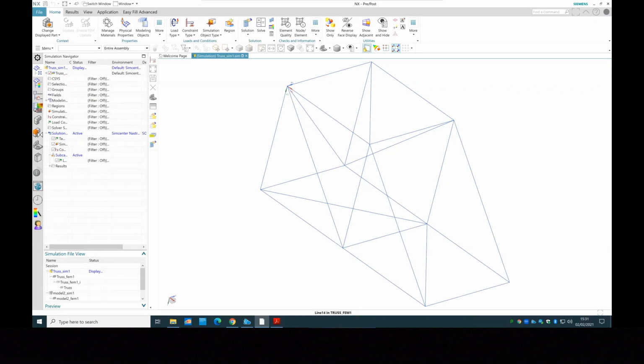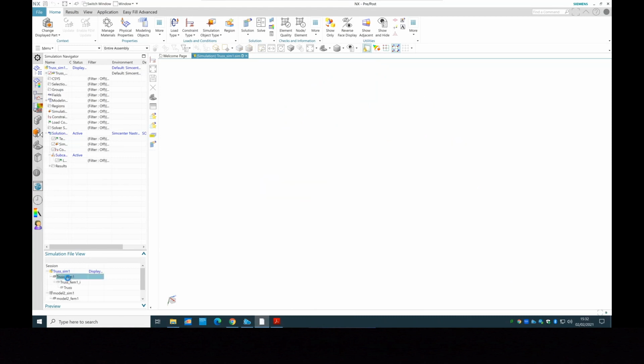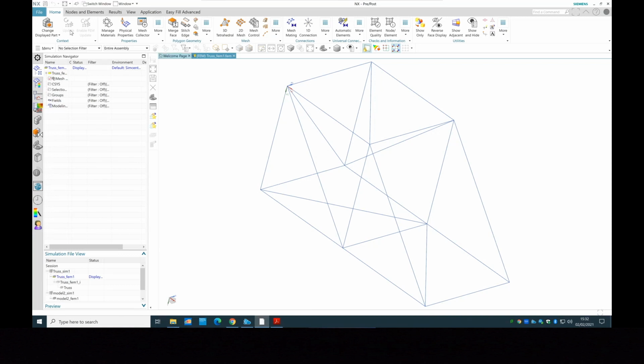First, you need to apply the mesh. You want to make it into smaller pieces. So what I need to do, I need to go to the mesh level, I double click to come to the mesh level. And if I go there, you can see the mesh toolbar would appear. What I will do in this case, because I have just the lines, I want to use the 1D elements. If it was a 3D model, then there are two options. You can do the 2D or 3D mesh, which we'll discuss next week. Not next week, the week after, next tutorial session.